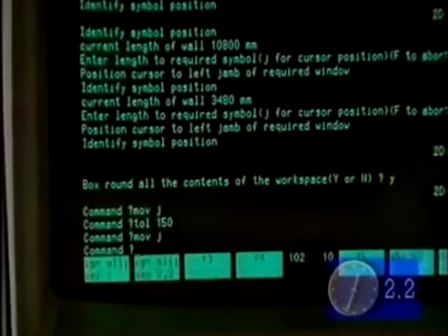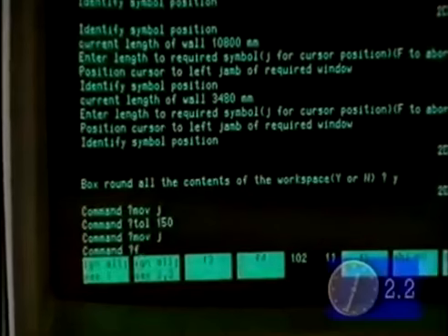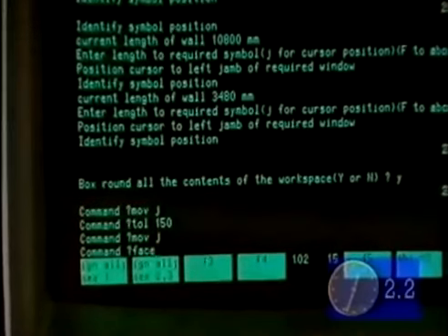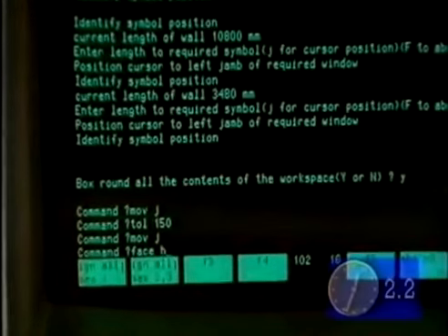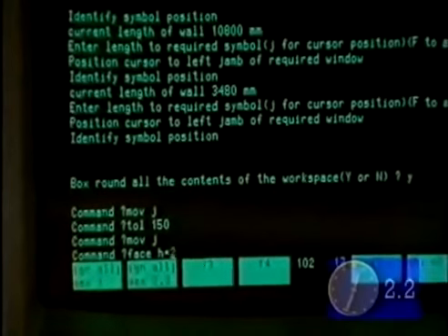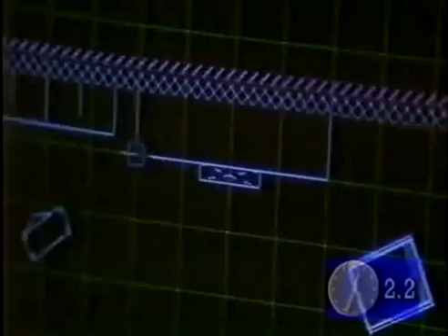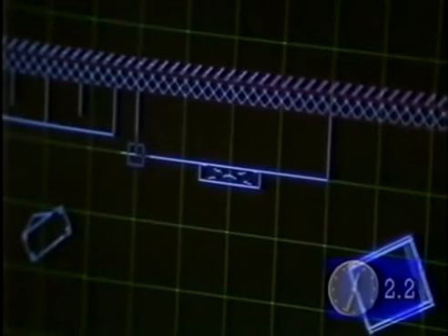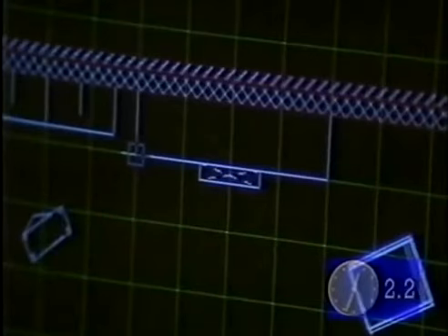So again, it snaps onto it for me. I then issue a command called face and specify a hatch to it. So if I say face hatch equals, well, if we're going to use block work, hatch pattern 2 is the block work. Right. And predefined pattern. That's right. And again, it's prompting us for a vector description, which, as we did earlier on with the lines,